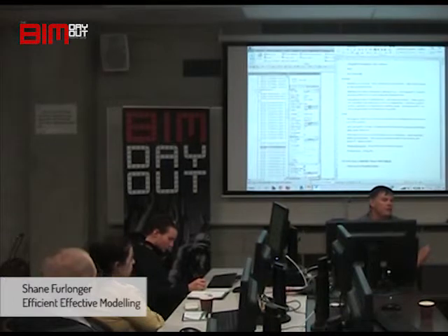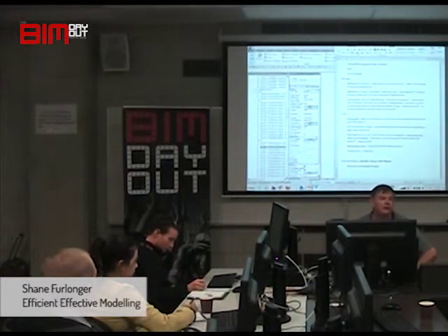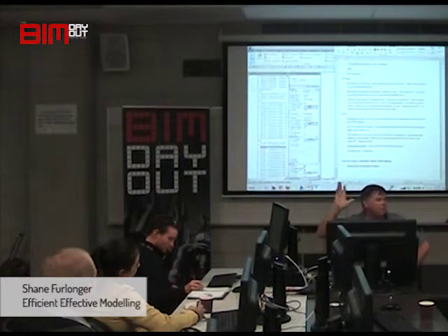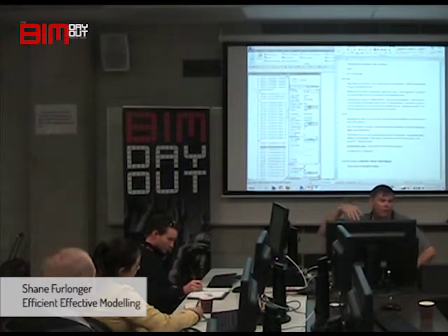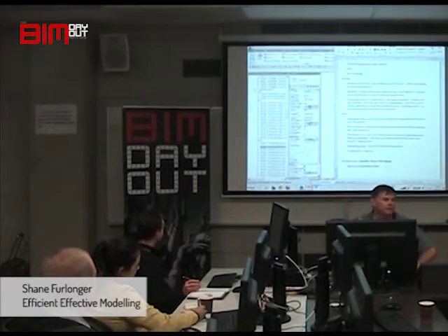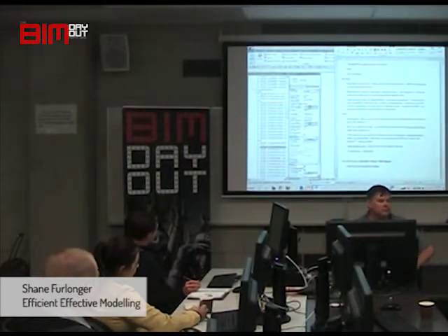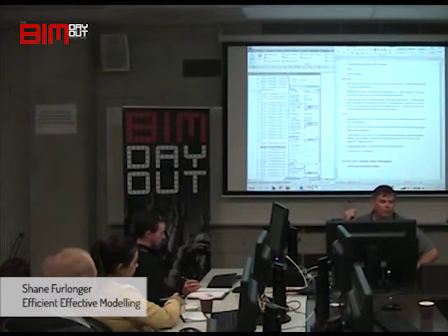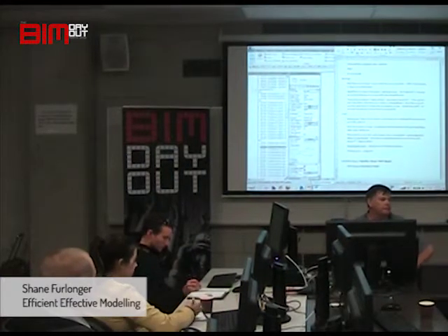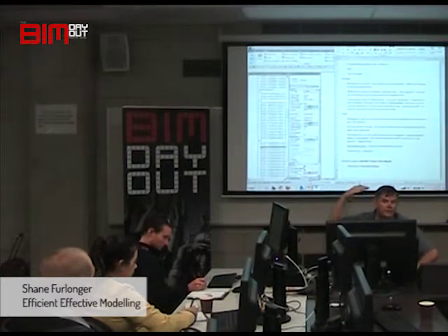And I suggest that when you are putting things on a ceiling, don't. Because if someone deletes the ceiling, you lose all your items. So if you've got lights, fans, ceiling hatches, whatever, that are face-based or level-based or whatever the case may be, don't attach them to your ceiling. Because when you delete the ceiling, all those items fall off your model. Put them on a reference plane so that they just sit there all the time.